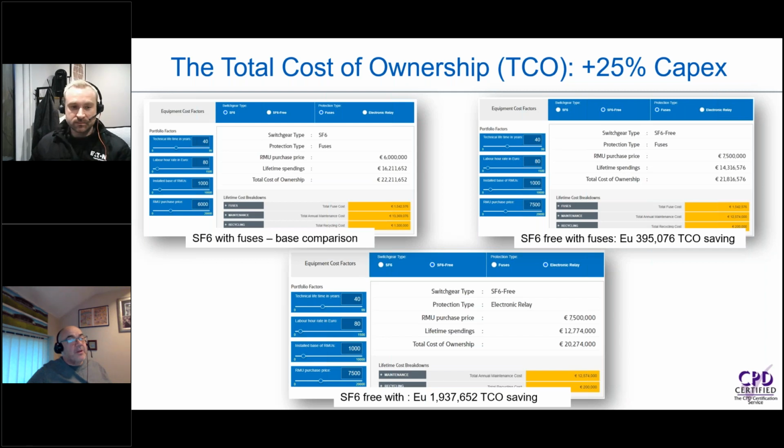Yeah, and end of life is a big one, isn't it? It's expensive now to mitigate SF6 at end of life. Nobody knows what it's going to cost in 30, 40 years to get rid of it. At the moment, it's probably cost neutral or cost minus really to decommission an equivalent SF6 free system. The vacuum bottle is made of copper and alloys and ceramics, which are all fully recyclable. The cast resin is fully recyclable. The steel that it's in, there's a few bits of plastics that again are recyclable. So I think it's about 99% recyclable, the one we've got, or the similar systems.